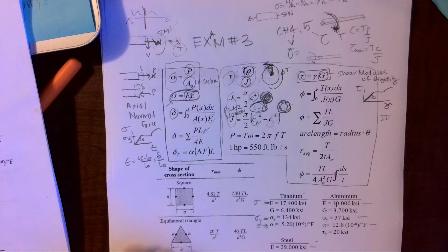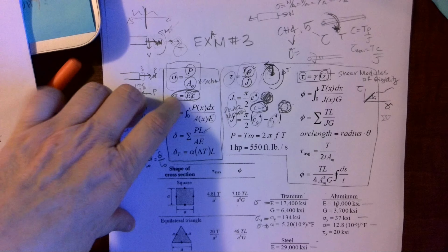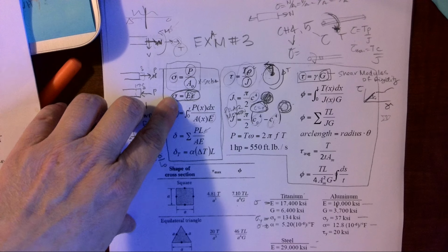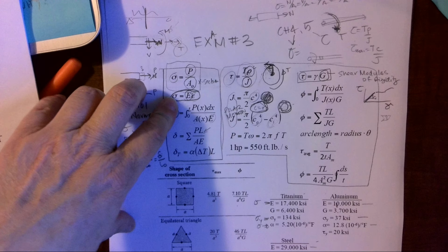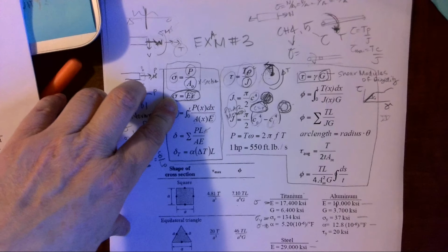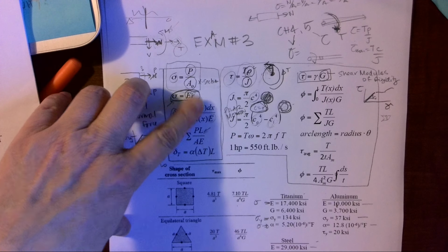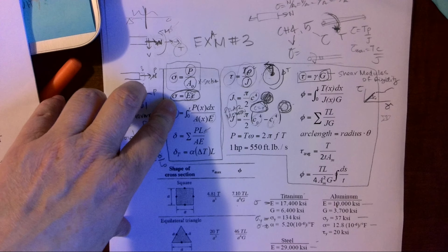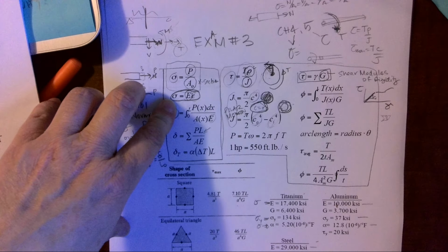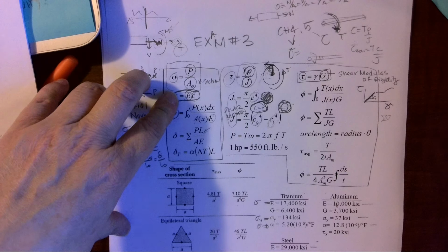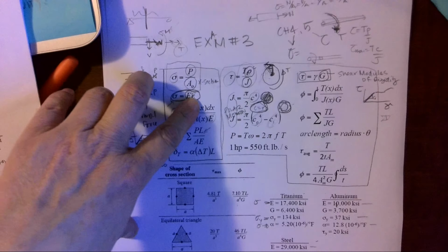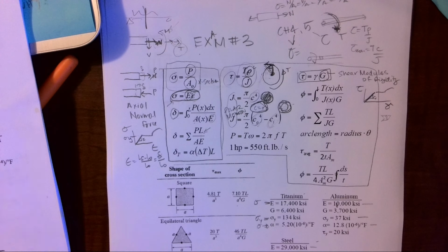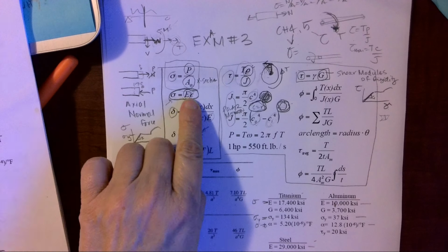So I have stress, I have material property, I have deformation. If I put a force which causes stress on a rubber band and I get a deformation, that strain is going to be much, much larger than if I have the same diameter of steel and I put a force on it which causes the same stress that I had on the rubber band, but this time my deformation is going to be much, much smaller, because they may have the same stress, which is just a function of load and area, but their deformation is a function of the material that we have.